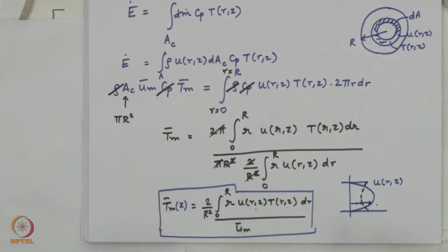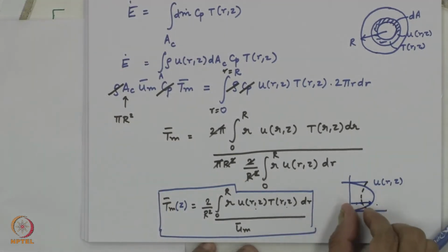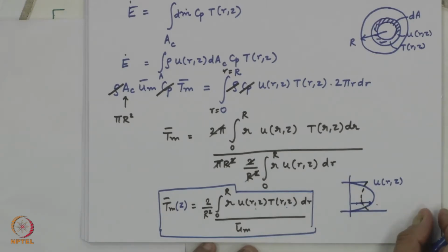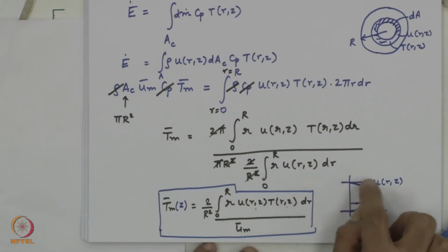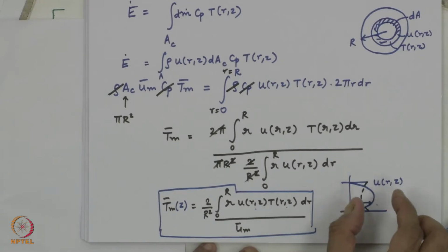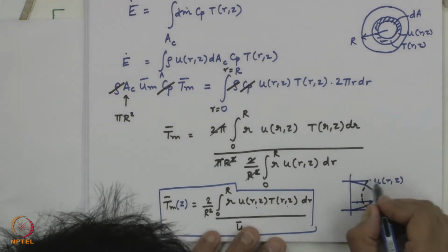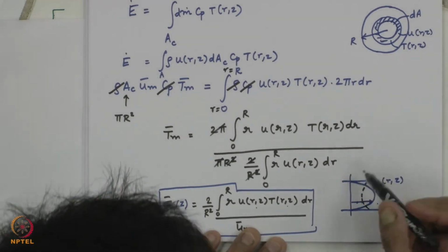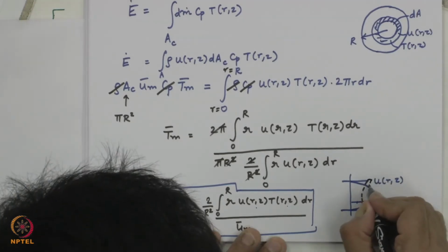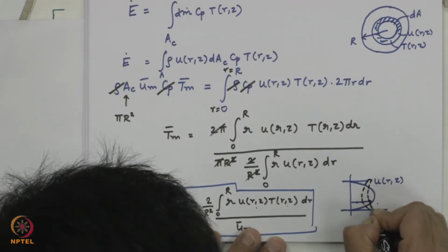So, it is this combined curves which are going to move in the z direction. This velocity curve is fixed, the temperature curve is becoming bulkier, bulging in the center and at the wall because heat is being added. So, at the next location I would have a temperature curve which looks like this.